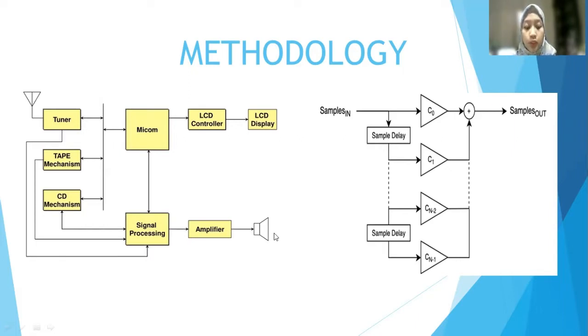For our project we're using an FIR filter, which is a filter structure that can be used to implement almost any sort of frequency response digitally. An FIR filter is usually implemented by using a series of delays, multipliers, and adders to create the filter output.